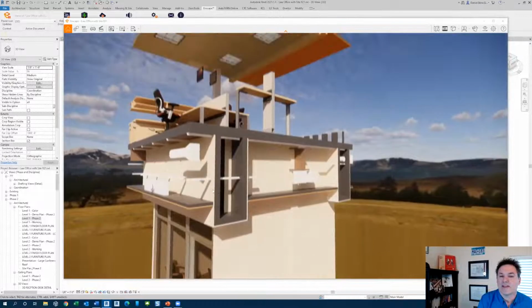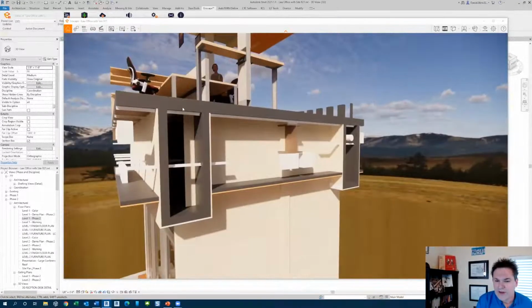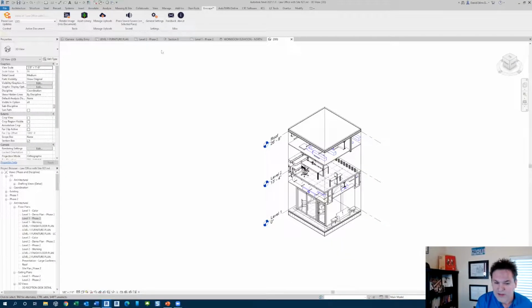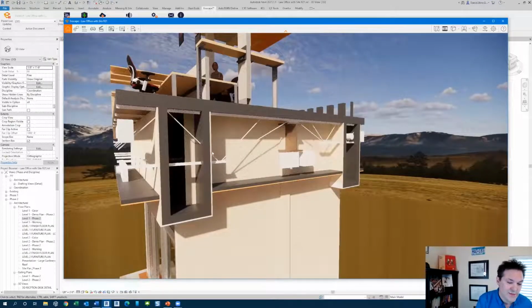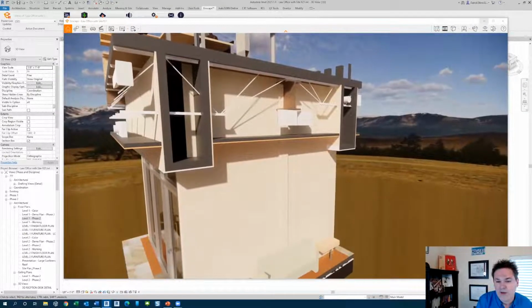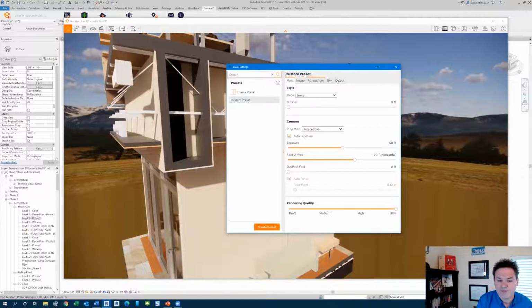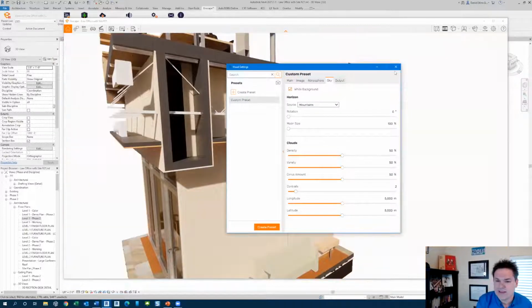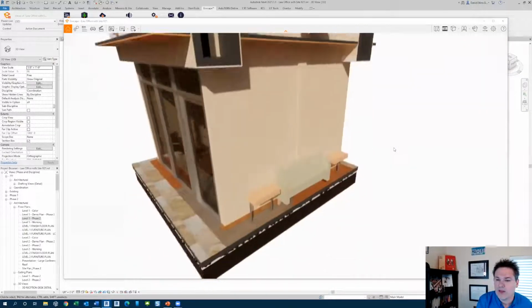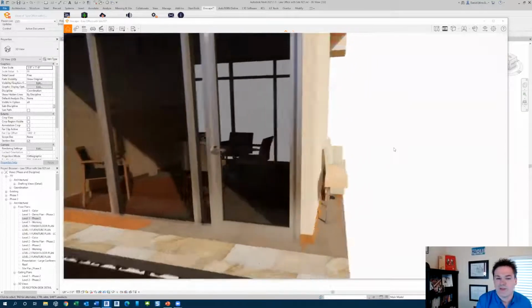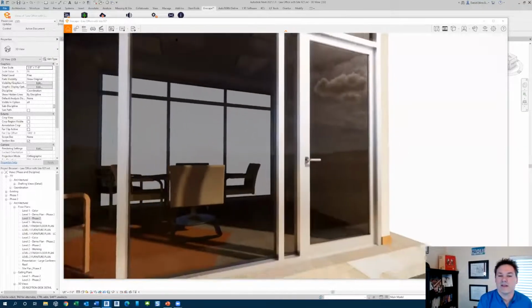And so we have this nice cutaway view. And actually, if you have a look at the bar joist here, you only see the top and bottom part of the framing. That's because Enscape honors Revit's level of detail setting, which can make Enscape faster, but not look as interesting. So now we have the bar webbing showing up. We might also want to set this to be just a white background for this particular look at the model.